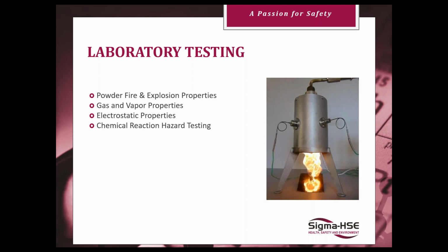Okay, because it works. There are, of course, a large range of hazard identification tools out there, some of which are a lot simpler, the use of checklists, what-if analyses, and things like that. But it's all what we call in the UK horses for courses. You can indeed use HAZOP as your main hazard identification technique, but as you'll find out from this webinar, it's quite resource intensive. And for simpler hazards, if you're looking at the hazards of transport operations on a facility or whatever, HAZOP would not be your most favoured tool to use. There are other ones there, okay?